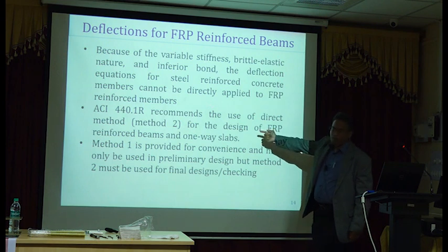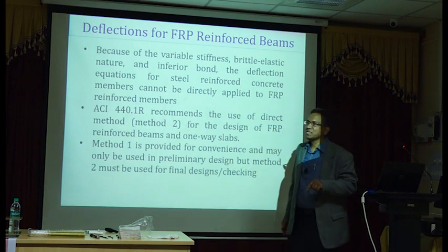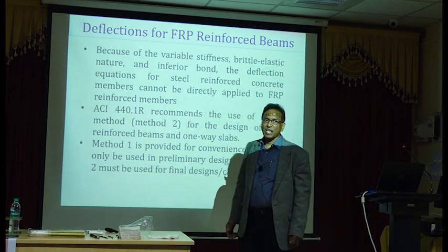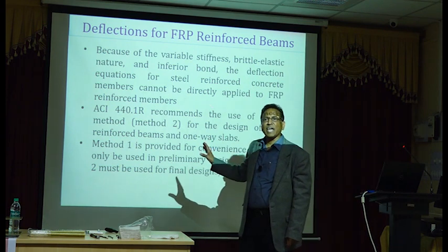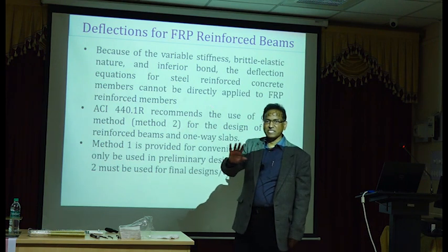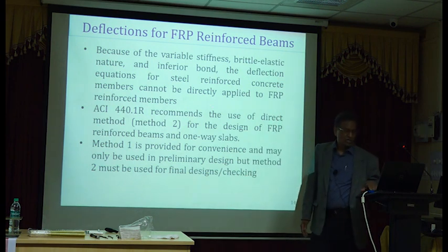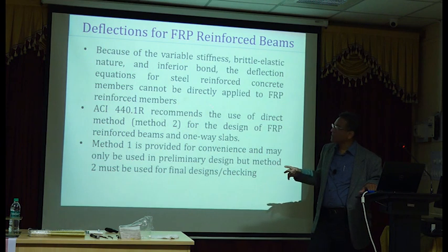However, ACI 440.1R still gives you the minimum thickness recommendations, but that's only for preliminary design. For final design, you cannot use those minimum thickness requirements and say deflection is satisfied. Okay, so that's a very, very important difference. So you must use the detailed method for calculating deflections.